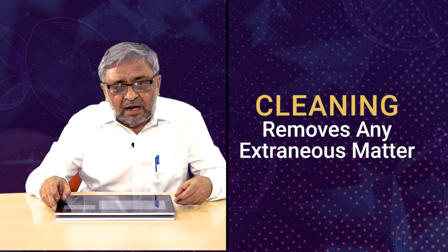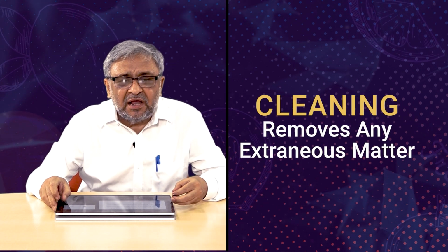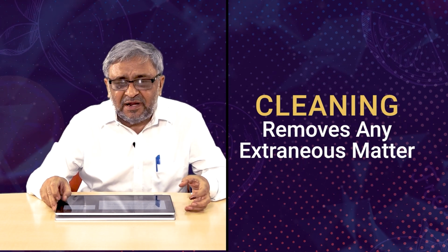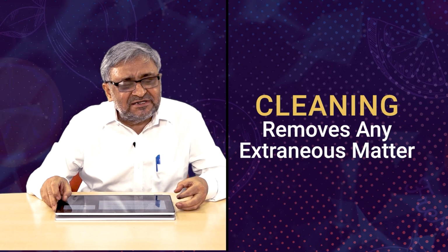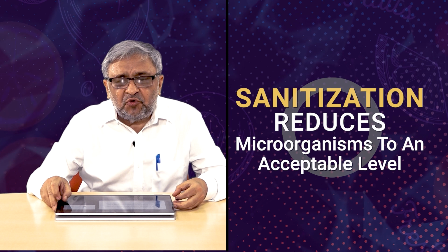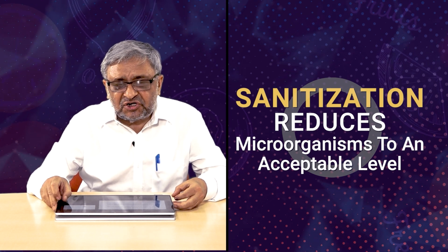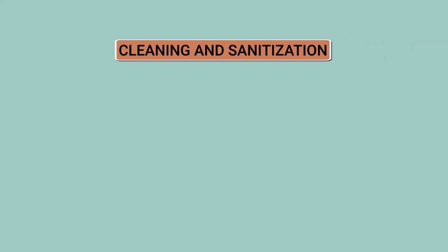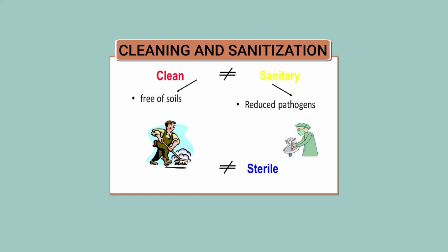The cleaning and sanitization, there are two different terms. Cleaning is to remove the extraneous matter adhering to the equipment, and it is done with a suitable detergent and water. And sanitization is reducing the microorganisms to an acceptable level, in terms of destruction of pathogens and minimizing the other microflora. So you can see this picture shows you. When you clean, it is free of soil, but sanitization reduces the pathogens and makes it sterile, meaning free of pathogens.